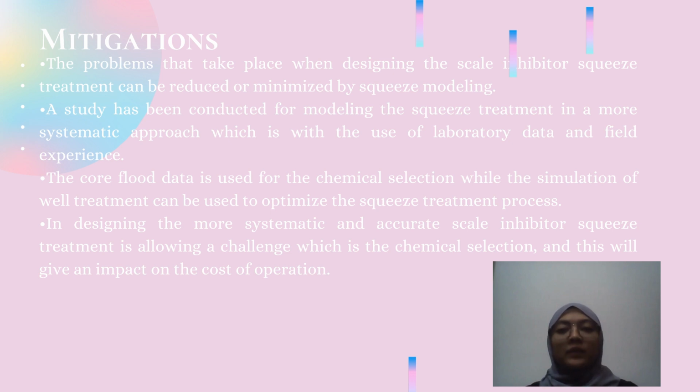The problem that takes place when designing the scale inhibitor squeeze treatment can be reduced or minimized by squeeze modeling. A study has been conducted for modeling the squeeze treatment in a more systematic approach, with the use of laboratory data and field experience. The core flood data is used for the chemical selection, while the simulation of well treatment can be used to optimize the squeeze treatment process.